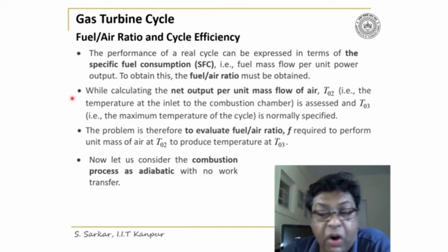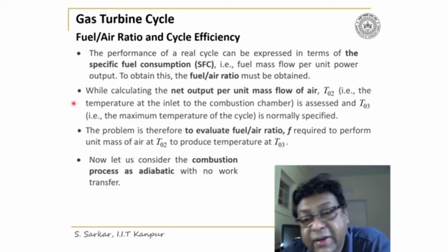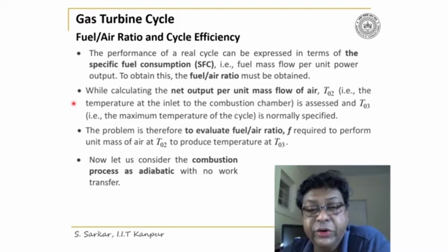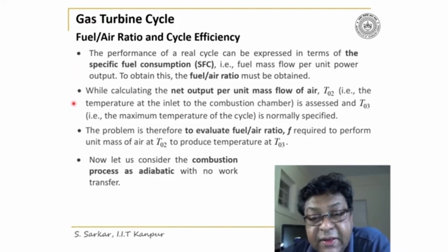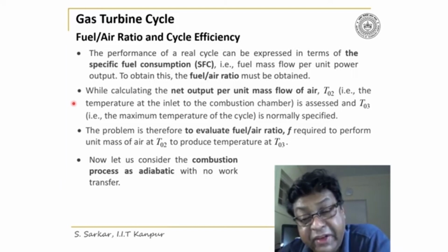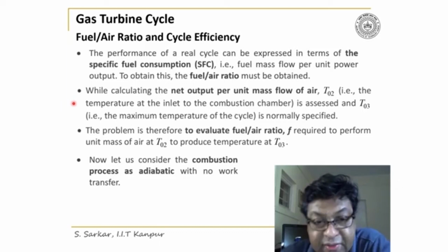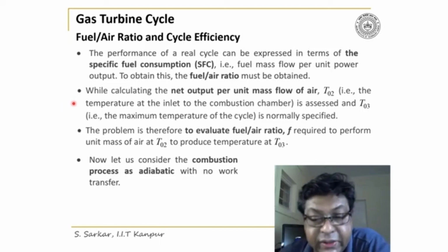That is what I'd like to say here, that T02 will have to be assessed and T03 is given, which is the maximum temperature of the cycle for any cycle analysis.